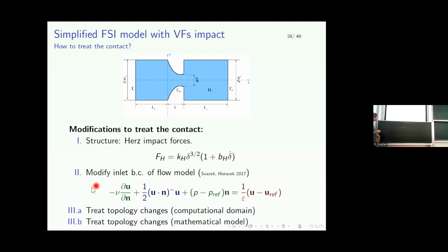So this is the nonlinear do-nothing boundary condition, which prevents the vortices leaving the domain from creating an additional amount of energy going backwards into the domain. So this somehow stabilizes the outlet condition when the vortices are leaving the domain. And okay, we modified this equation by adding this term. This is somehow motivated by Babuška's penalization boundary condition.